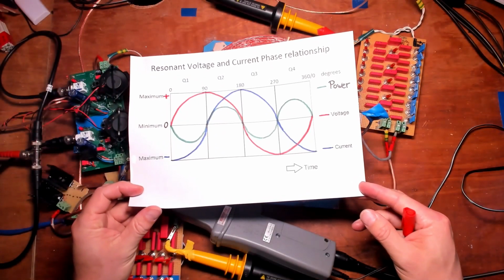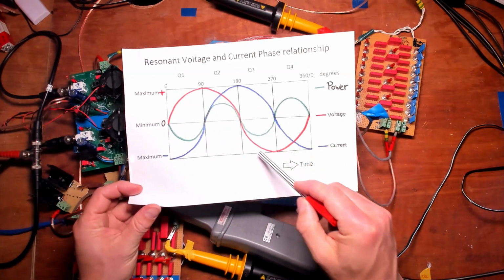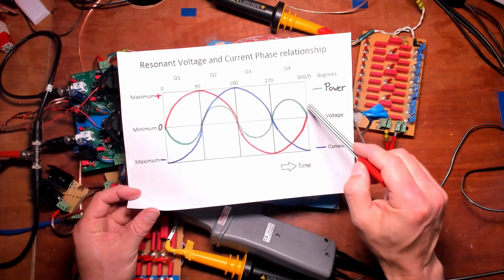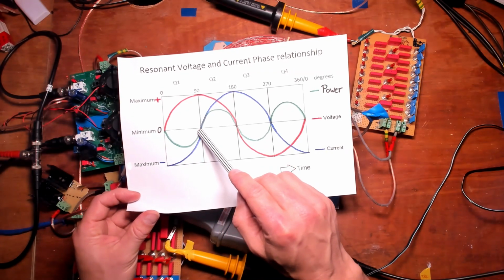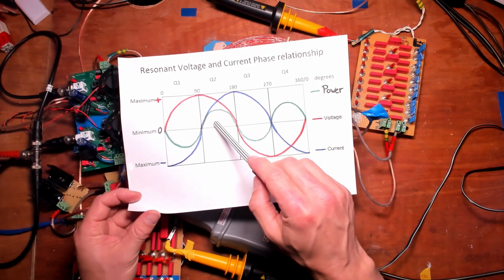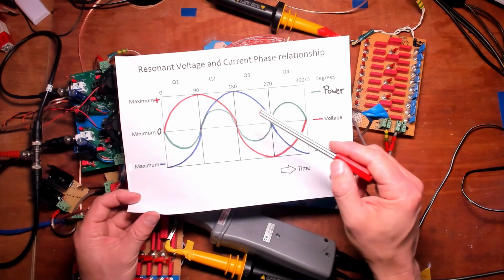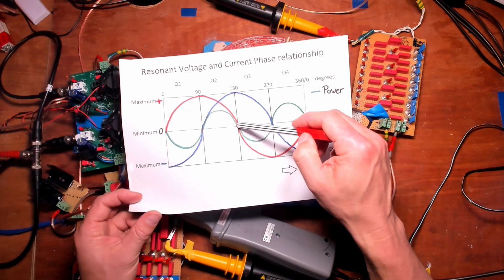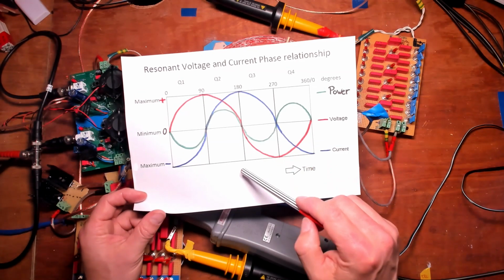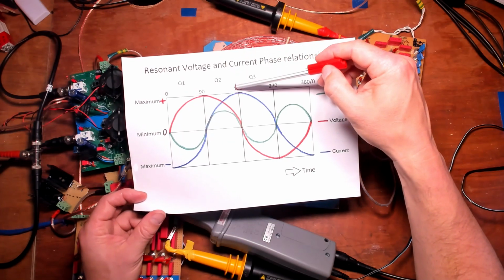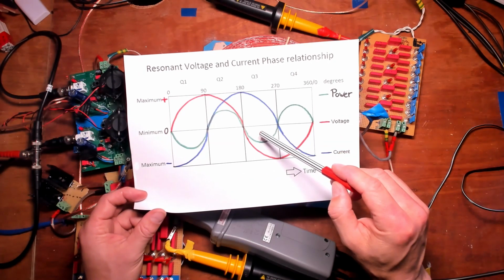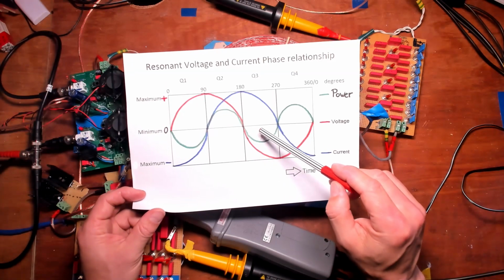Here again is the phase relationship between the red voltage of L2, the blue current of L2, and the power cycle that it generates, whereby the negative cycle is a power generation and a positive green power is a power consumption. So by placing the impulse here on the voltage minimum of L2 in red, we can combine it with the current maximum, positive current maximum, and we'll have a power moment at the start of the negative power, where the power is being generated by the coil.